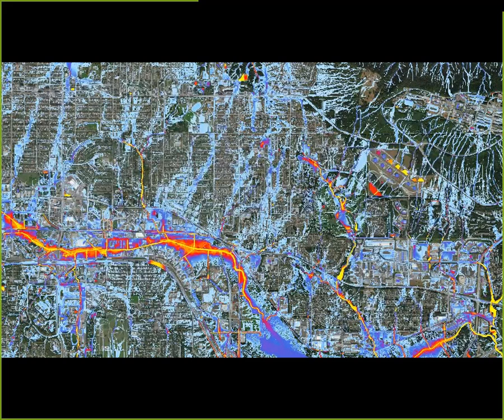So we did that, and here's a static kind of picture of where the water flows. So you can see that there's an air photo with some blue, dark blue, purple, reds, yellows, and so on that are intended to signify the extents and depths of the water. So the very light blue represents really quite shallow flow, but it also shows you the concentration paths of this water when it's flowing through the community.